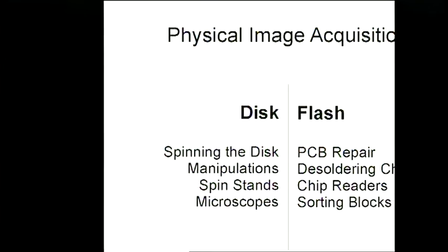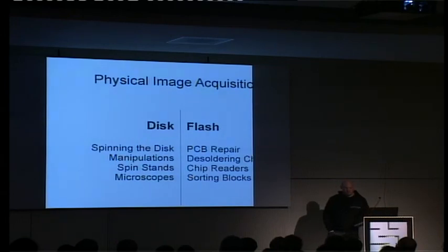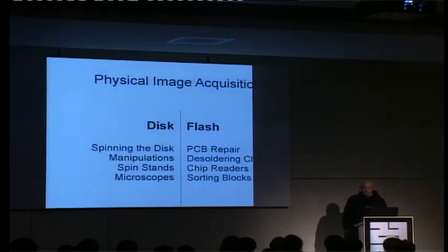But I can tell you, today it is almost impossible to get the platter centered on the spin stand so that you can accurately read it without evaluating the servo information. So spin stands today are only for engineering purposes. They are not used, to the best of my knowledge, for data recovery purposes.